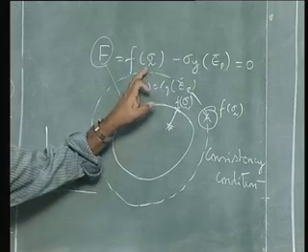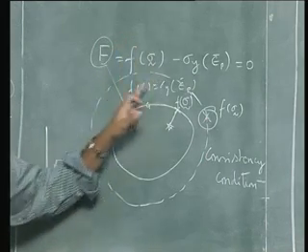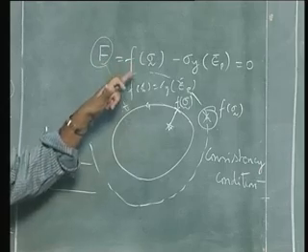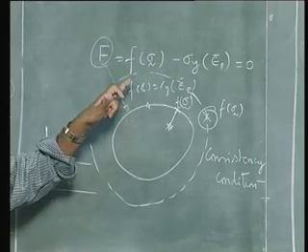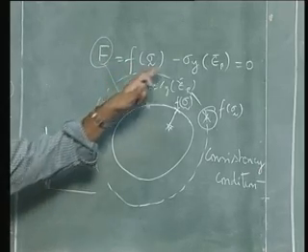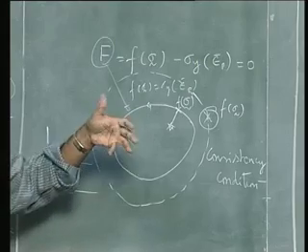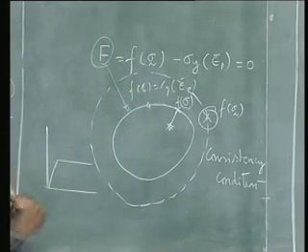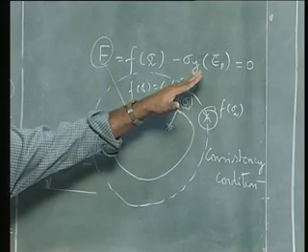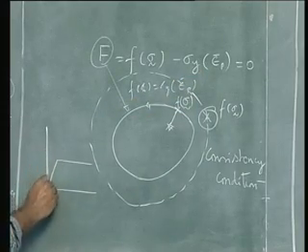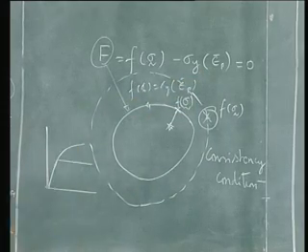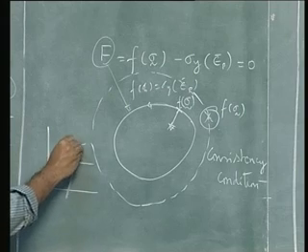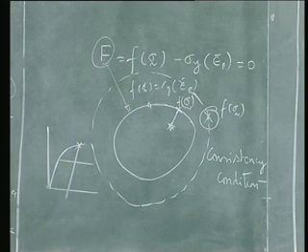Obviously, when I reduce this F, okay, which is called unloading, whatever has happened to the material, the response of the material does not revert and is left as it is. And that is why when I have this picture and when I unload, my yield point remains there.